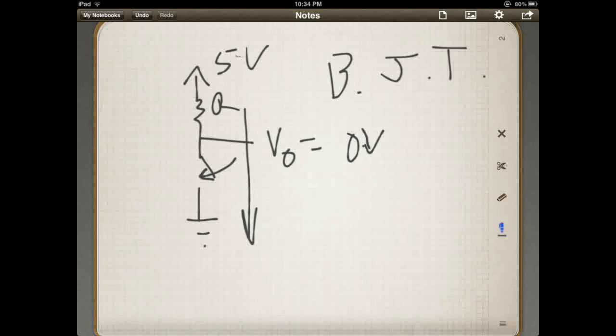Other situations, let's say if you have different grounds separated by different values, it might not be good to switch the ground. Switching the ground could cause you to lift a ground in parts of the circuit that you don't want lifted, and it could cause potential differences that could cause current to run backwards and weird stuff like that. So there are situations where you want to use a high side switch.